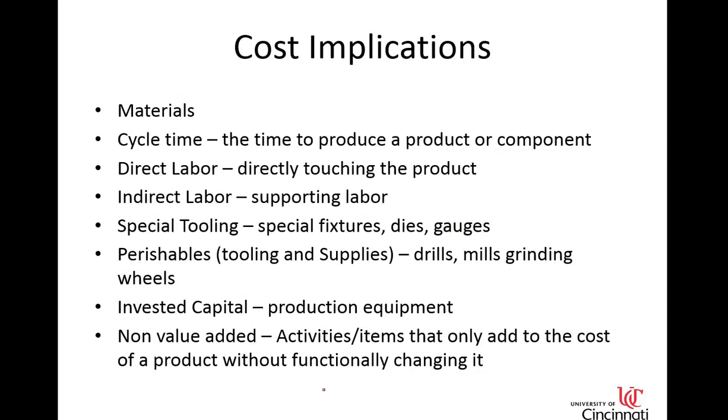So again, cost implications: there's implications through the materials, the amount of cycle time, direct labor, people who actually have to hold and handle the part, indirect labor, anybody supporting it, the water spider, the person who has to run your materials, special tooling, perishables, things like drills, mills, grinding wheels, invested capital.